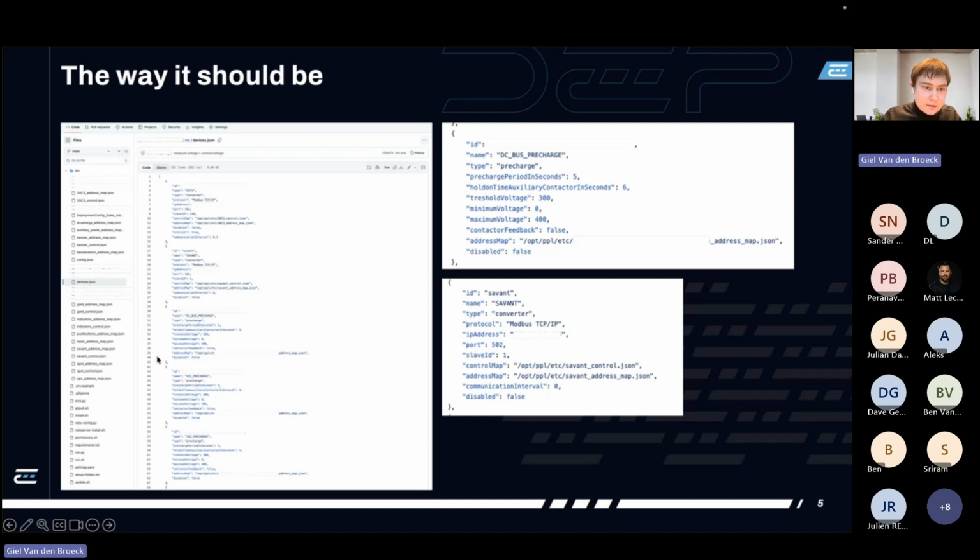And this file, as you might have already noticed, lives on GitHub, a system that's well known in the software space for version control. So I can go in here and make changes. Here on top, for instance, it shows what the latest changes are. So this change happened last year. It has a particular ID. I can go back in time. If something changed in my configuration that broke something, I can literally go back to the last working state and have full traceability about what has been changed, when it has been changed, and by whom. And these files can then be downloaded directly onto the controller. So again, an efficiency gain and a time saver.